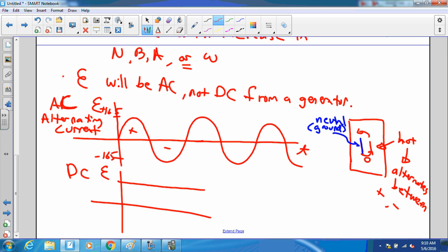Well, how quickly are the cycles? That also depends on what country you're in. If you're in the United States, the frequency for alternating current is 60 hertz, or 60 cycles per second. That means that the period of one cycle is going to be 1/60th of a second, which is very, very fast. That means that the alternating is not like this, boom, boom, but like this, even faster. It's going to be alternating back and forth like that.